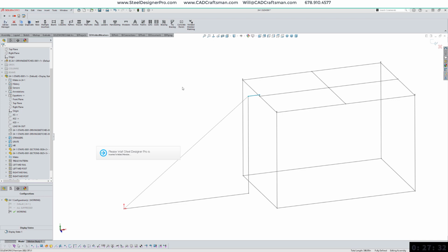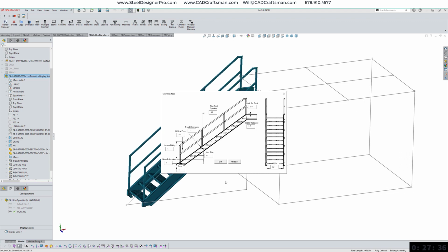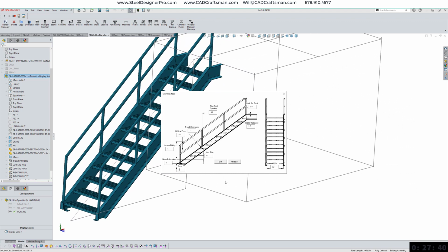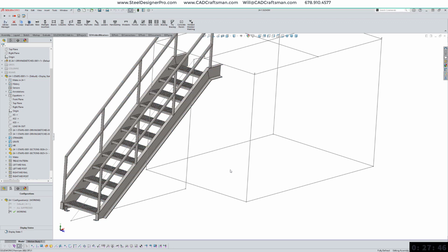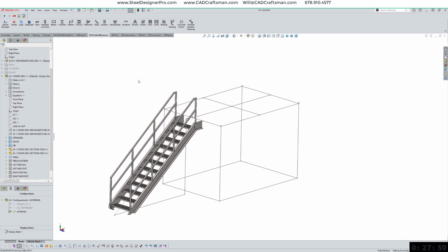The interface allows for changing many of the parameters of this stair. For complex members with driving sketches that are hidden, there are times when SOLIDWORKS fails to process items correctly and faults appear. This is easily fixed by showing the driving sketches and rebuilding the model. It may take a few rebuilds. Now we can measure the overlap of the beam flanges and add grating to the platform.